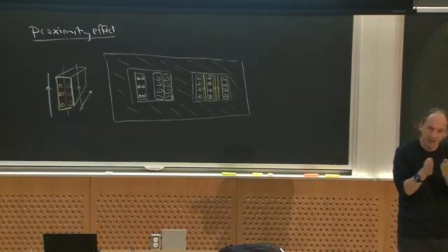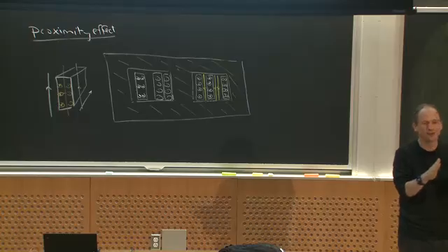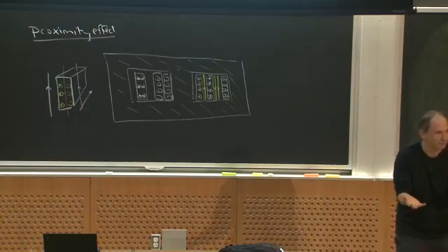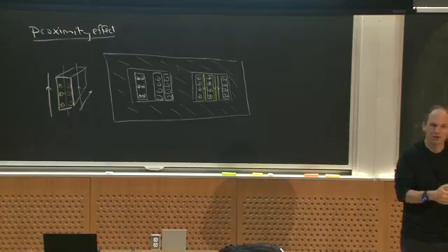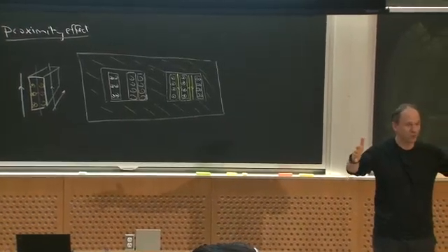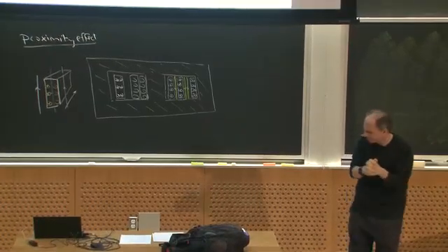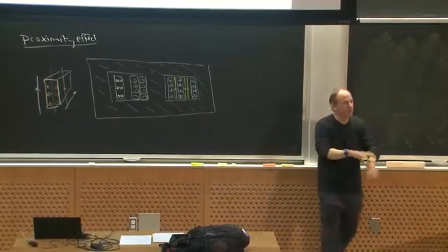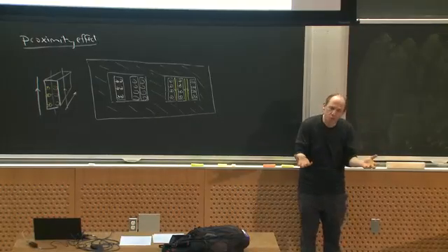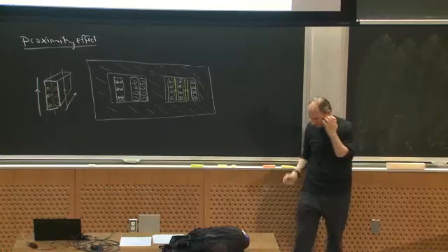If you include proximity effect, very often you want your strand diameter or your wire diameter to be maybe 0.3 skin depths, or you get into this weird situation, and so sometimes that forces you to use really fine wire, really small strands, even smaller than a skin depth. So think, 0.3 skin depths might be what you'd get if you had a lot of layers.